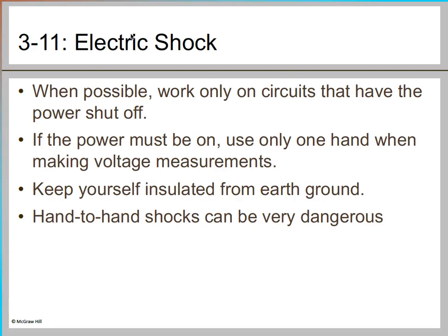Keep yourself insulated from the earth ground, and that will protect you from any electric shock. Hand-to-hand shocks can be very dangerous because the current in that case can flow through your heart, and that will not be good for you. So make sure that you don't do that.